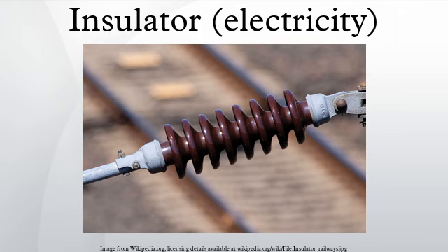In electronic systems, printed circuit boards are made from epoxy plastic and fiberglass. The non-conductive boards support layers of copper foil conductors. In electronic devices, the tiny and delicate active components are embedded within non-conductive epoxy or phenolic plastics, or within baked glass or ceramic coatings. In microelectronic components such as transistors and ICs, the silicon material is normally a conductor because of doping, but it can easily be selectively transformed into a good insulator by the application of heat and oxygen. Oxidized silicon is quartz, that is silicon dioxide, the primary component of glass.